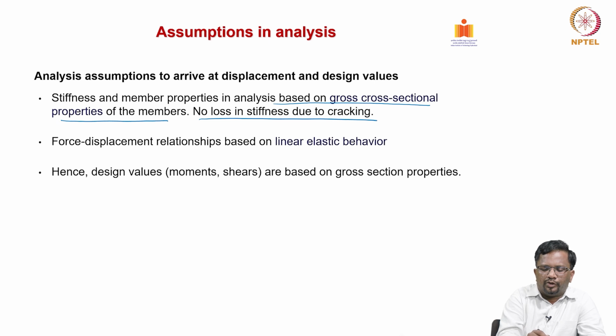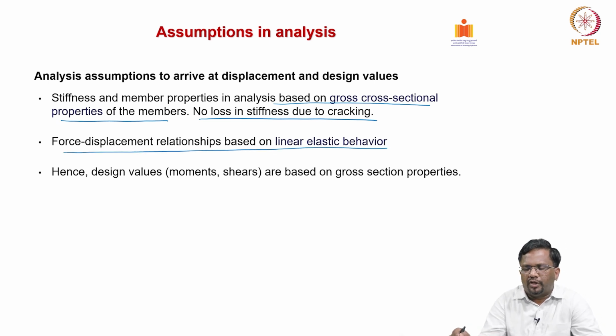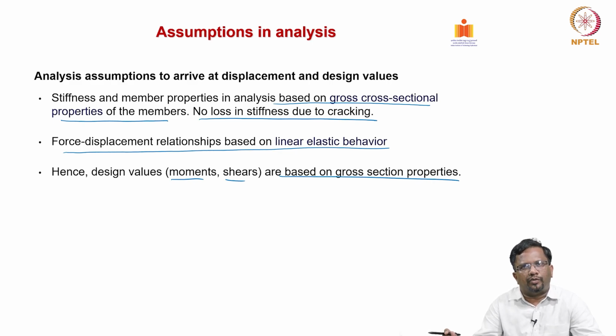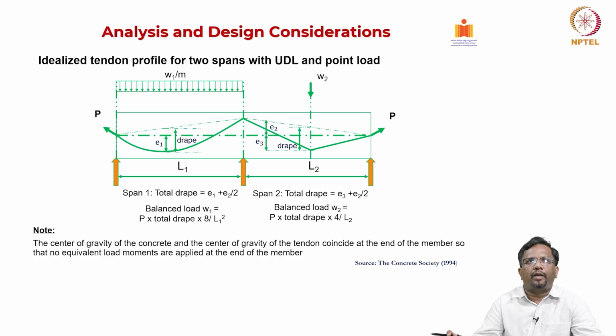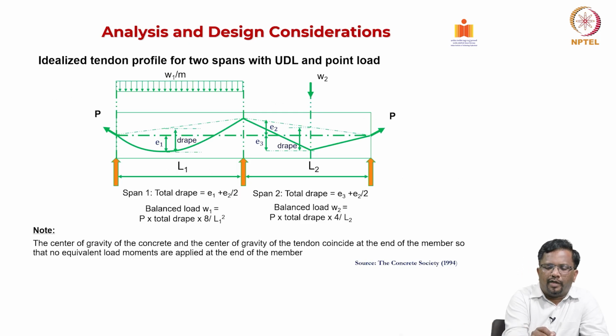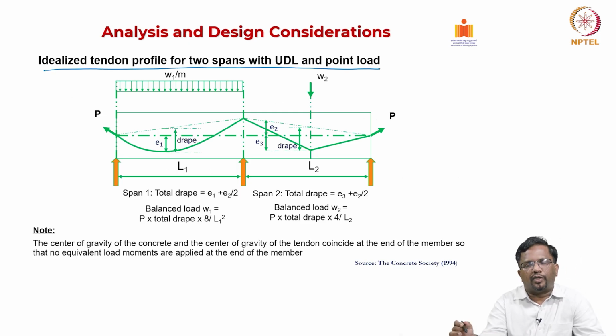And we are also going to assume force displacement relationships based on linear elastic behavior. So, the design values, moment and shear, that you are getting from your analysis are based on the gross cross section properties. Basically, we are not going to consider cracking while we do the analysis to find out the internal forces. Also, when we are designing, it is based on the service condition, where it is assumed to be uncracked.